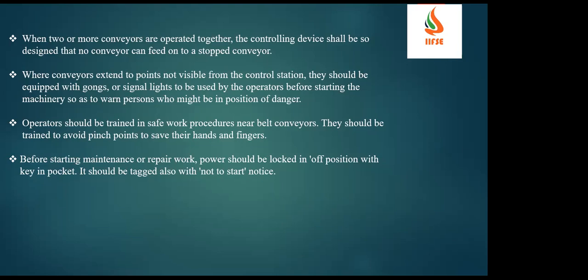Then the operator should be trained in safe work procedures near the belt conveyor, and they should be trained to avoid pinch points to save their hands and fingers. It is also necessary that all the maintenance operators, as well as whoever is working on the conveyors, get proper training about all these pinch points and nip points.